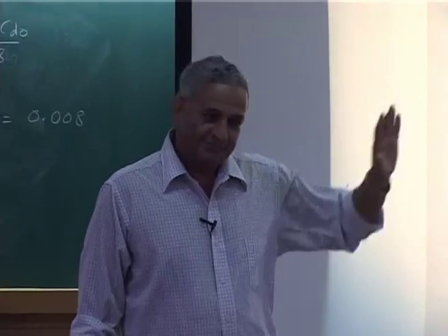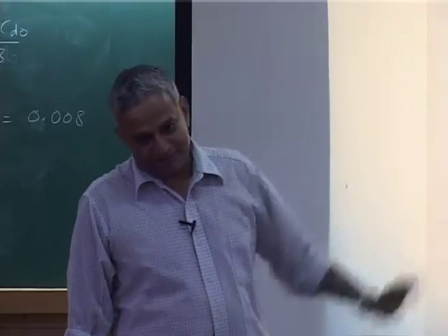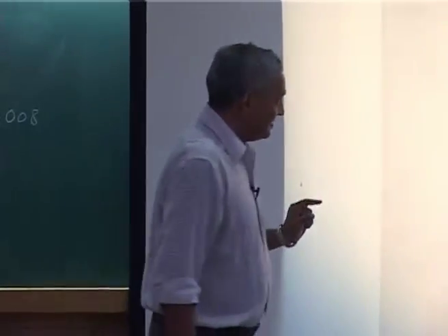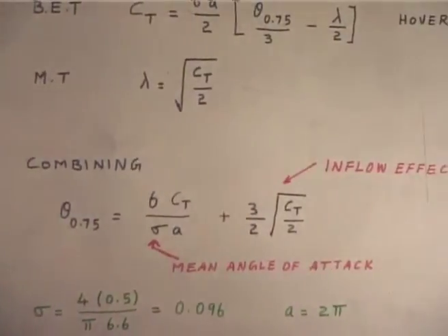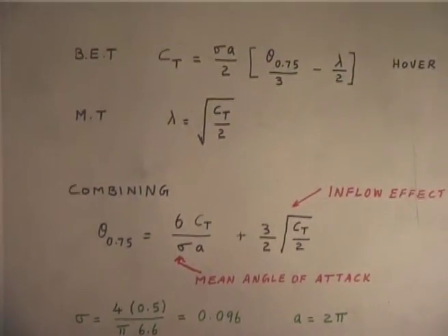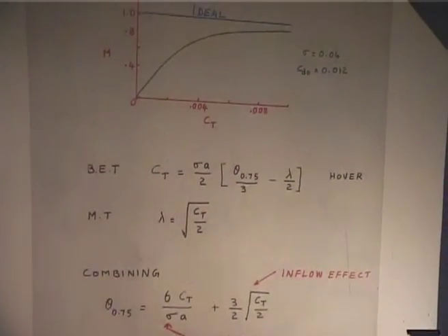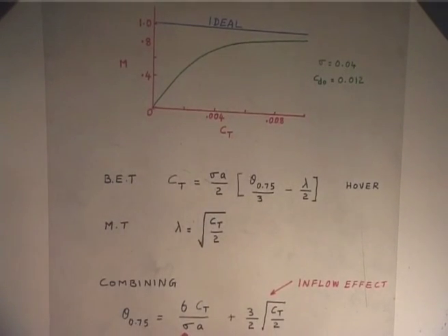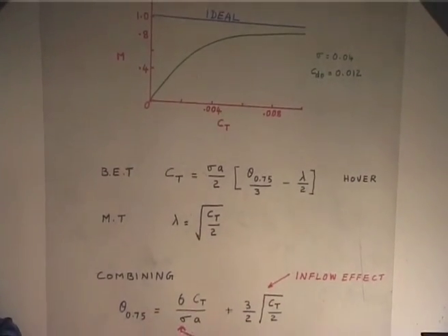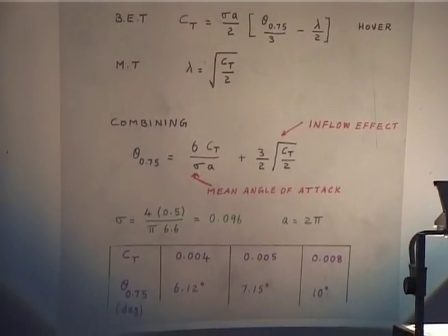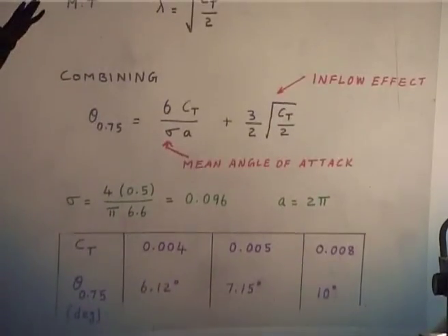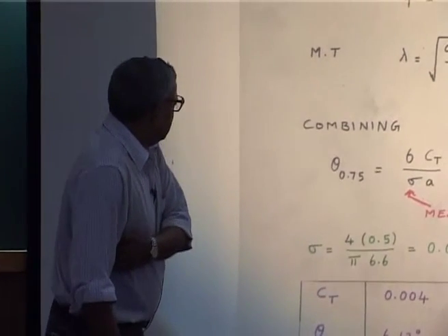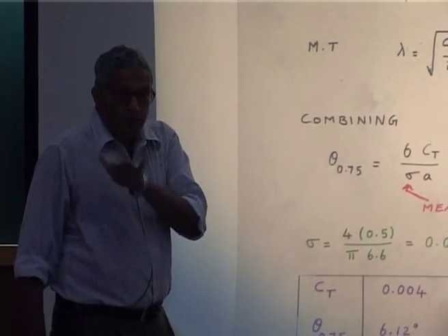If they do not make sense, then there is something wrong in your actual, very detailed calculation. So, that is why it is very important to understand the various expressions, thrust, inflow, figure of merit, theta, Cp, etc., all these terms. Till now we have learnt about the power and thrust for a rotor in hover and using uniform inflow.